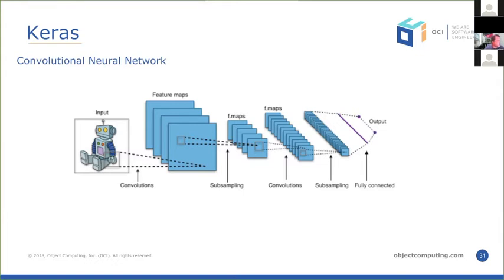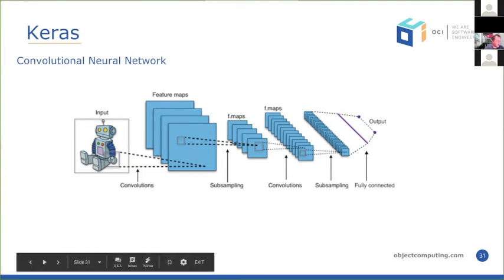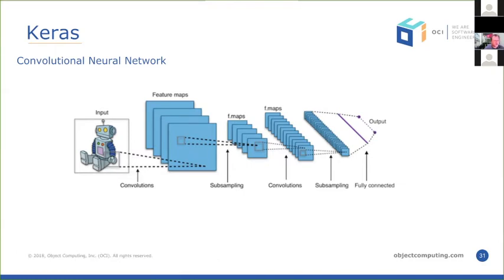What we're doing is we're taking convolutions, which are pictures of things and samples, and we're breaking those down into different convolutions and samples, all the way down until we finally get to an output. Basically, we're taking the input of learning a whole bunch of images and telemetry of driving, what our angle is of the servo, what our throttle position is, and we're turning that back down into output so that it can learn to drive at any given moment based on what it's seeing in the camera, which is 2 white lines, to either go left or go right and go forward or stop. And that's basically providing all of the guts of that.